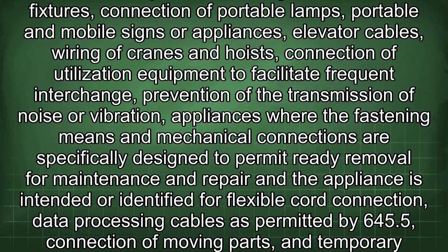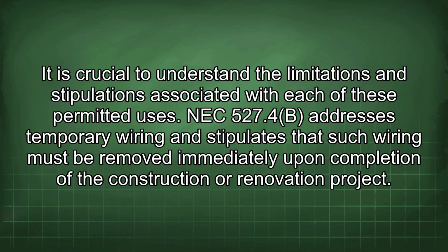Data processing cables as permitted by 645.5, connection of moving parts, and temporary wiring as permitted in 527.4(B) and 527.4(C). It is crucial to understand the limitations and stipulations associated with each of these permitted uses.